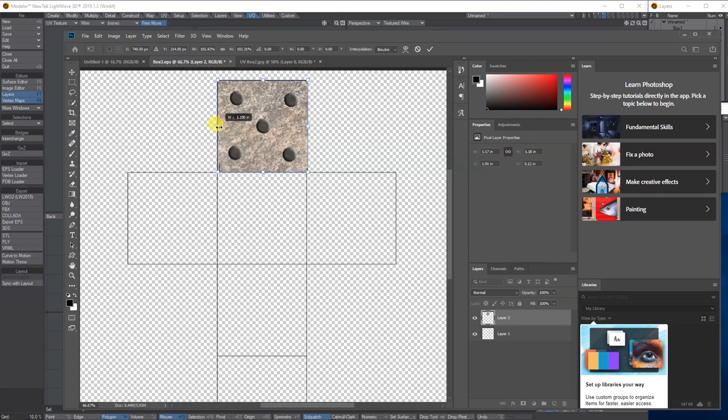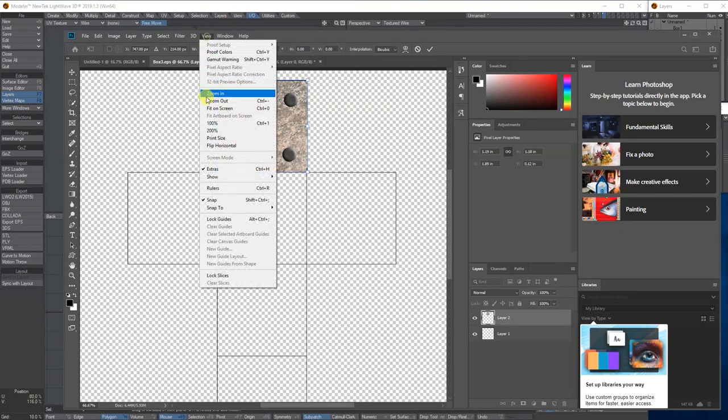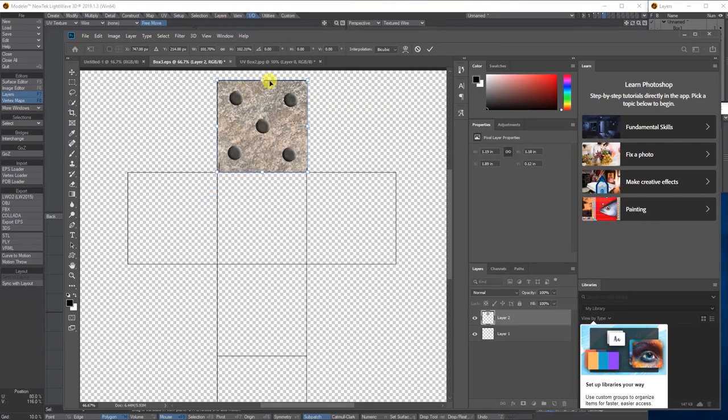What I try to do is always go over the line, maybe a millimetre or so. Make sure snap's not on. So you're going over it, so you're not going to get the black line. Pull it to the top, and then repeat the process with the others, which I will do now.